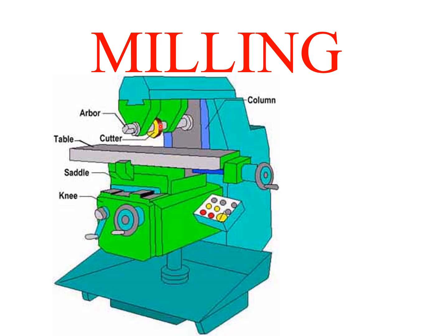Therefore, they should be selected reasonably according to the machining quality, machining efficiency, and machining procedure. Generally, machining efficiency is the first goal in roughing machining, so a larger cutting depth and cutting width should be selected. Quality of the workpiece surface is the main goal in finishing machining, so a smaller cutting depth and cutting width should be selected.